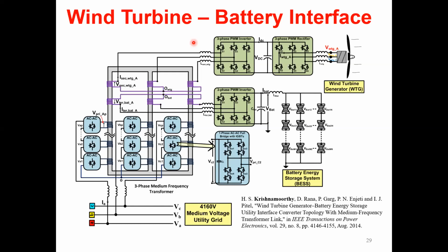These are the equations for the hysteresis and eddy current loss. Typically, the losses are a function of frequency and flux density. Whether it is eddy current loss or hysteresis loss, it's just that the power may change a little bit. If we increase the frequency, the loss per pound is going to go up significantly, because it's a power of 3 over the power 1.5, right?